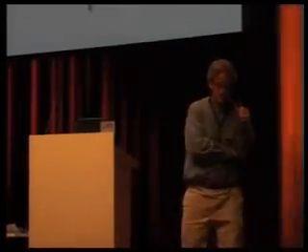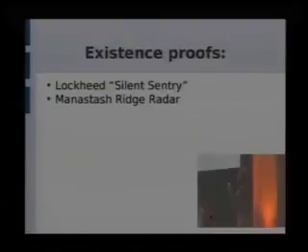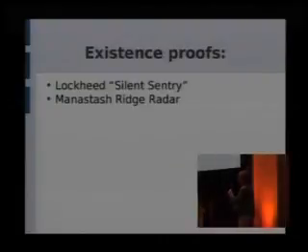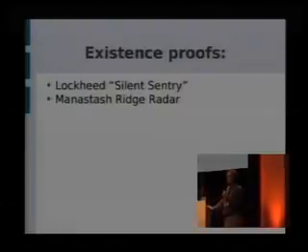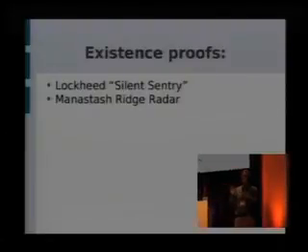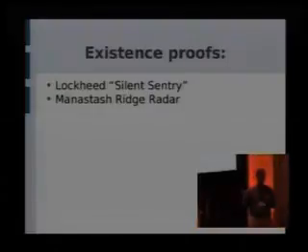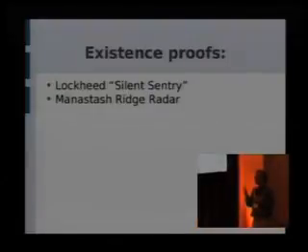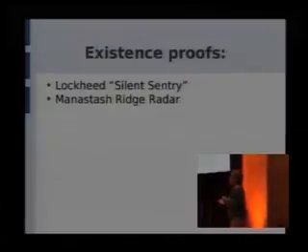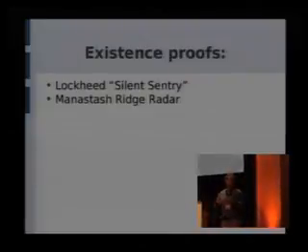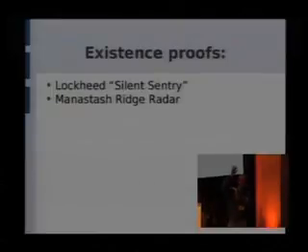Okay, so before we headed down this path, we said, are we totally crazy, or has anybody else done this? The top one here, the Lockheed Silent Sentry, is the money-is-no-object, let's-make-it-work approach. It was based on taking advantage of broadcast FM stations. What people like about FM is that the signals are all over the world, and they're fairly high power, not uncommon at 30 kilowatts. And because of the frequency range, they actually have good propagation characteristics.